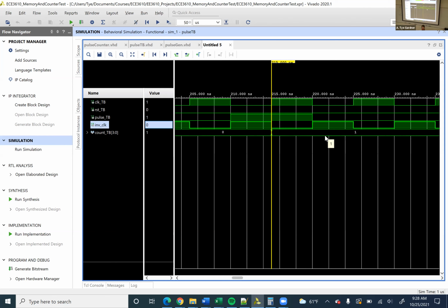So this applies to your SPI, right? If you're sending this pulse signal to your SPI, just use the pulse signal that generates half a clock period off of the thing that is telling your SPI when to run, and you will not have to worry about screwing up that system, like missing a data packet. And then you also don't have to deal with the load being always high, which is going to be very difficult when later I make you use variable data rates for your SPIs. Does this make sense to everyone? Okay, wonderful.